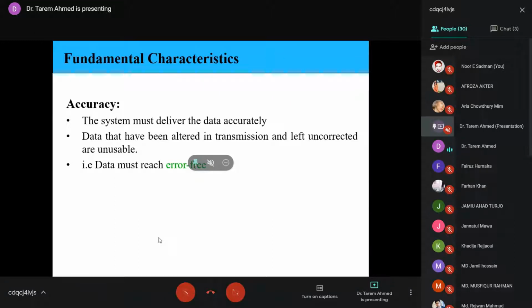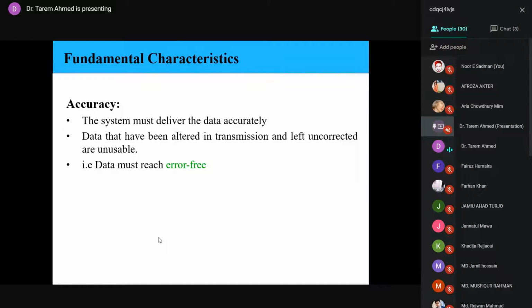Now, in this scenario, if a 5-volt becomes a 4-volt and a 0-volt becomes a 0.5-volt due to noise, a receiver is able to distinguish between the two. He'll see a 4. He knows that a 4-volt was not sent. Either a 0 or a 5 was sent. When you see 4, it's most likely closest to a 5, right? When he sees a 0.5, he knows this is actually nothing was sent. This 0.5 is actually atmospheric noise. Okay?